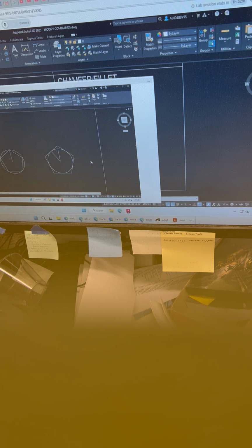So these tools up here that you use, they are not rectangle creators. They're not polygon creators. What they are are polylines that create rectangles. Or more specifically, as you can see in the tooltip, this tool creates a rectangular polyline. The polygon tool is a tool that creates an equilateral closed polyline.